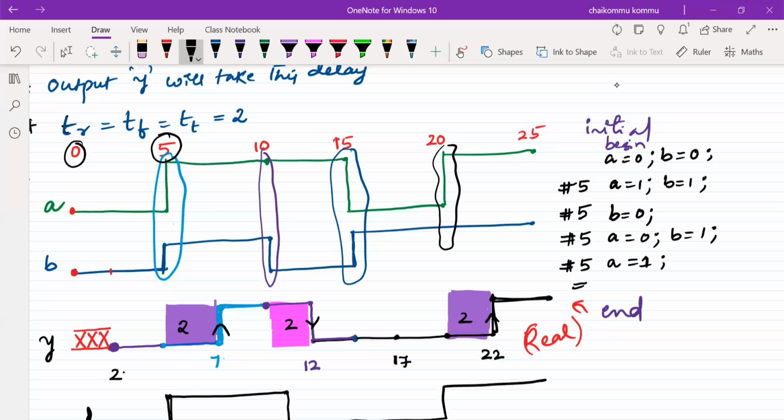But another 5 nanoseconds, at 25, both are not changing, right? So I want to keep it like that only. So whatever it may be. The simulation will stop at 30 nanoseconds, and up to 25, A becomes 1, B becomes 1. Okay, so this is how we need to write a Verilog program, the test bench information.